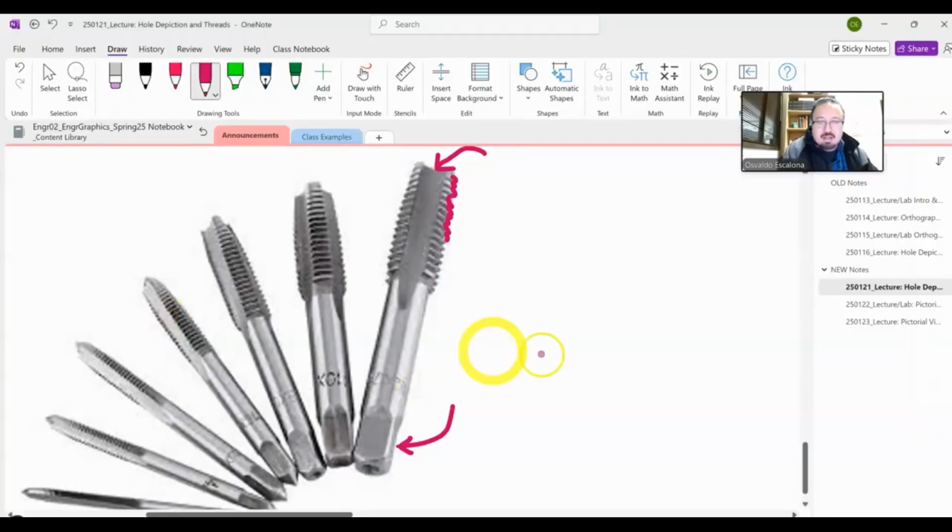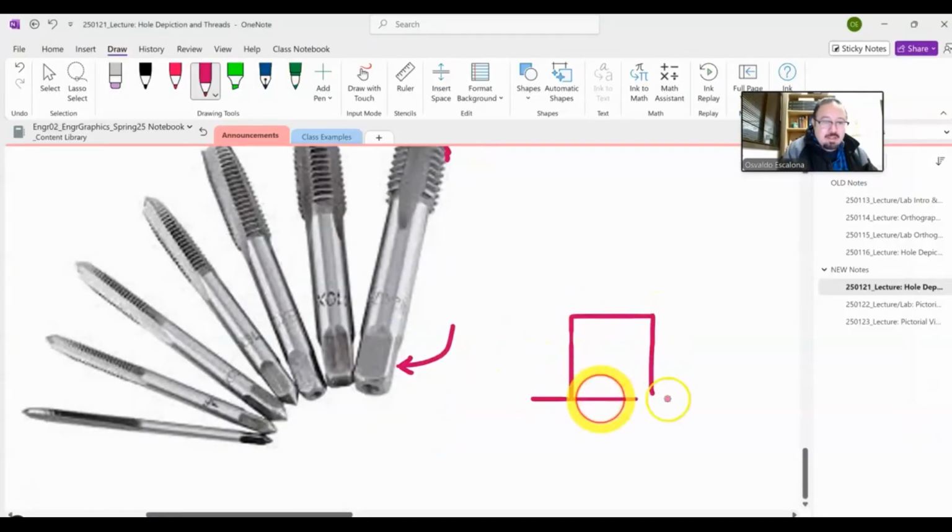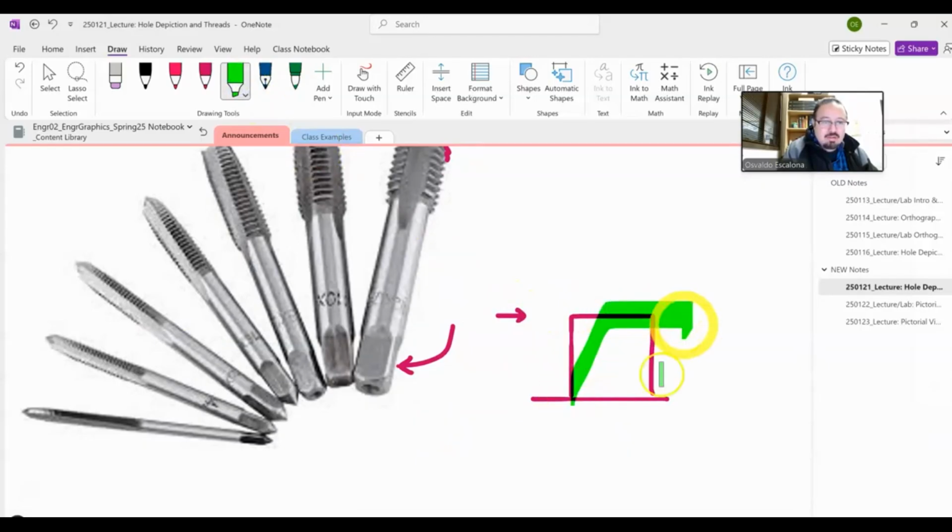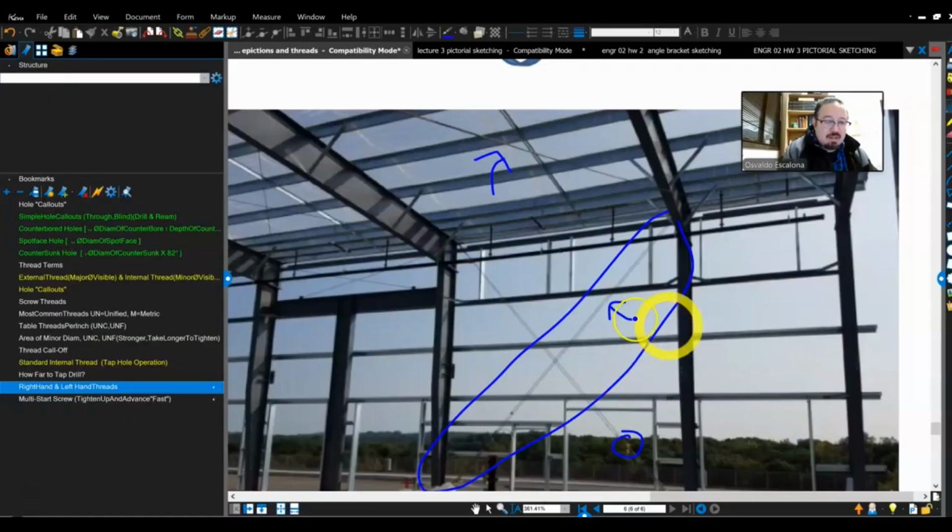If you have a building and you apply a load, the building is going to want to rock this way. But you have a cable that does not allow it to rock. So when this side wants to start deflecting, the cable goes into tension. And when it wants to deflect the other way, the other cable goes into tension. That's why you have these effects. Hopefully that makes sense.